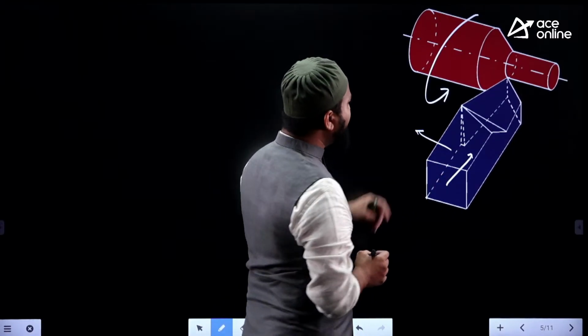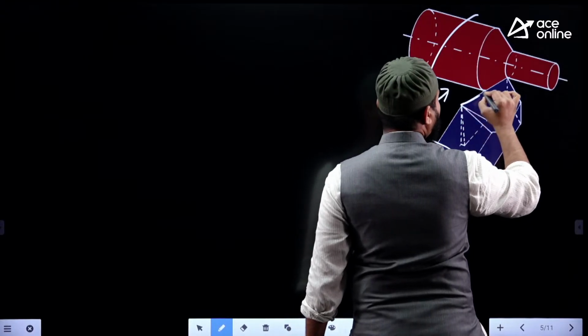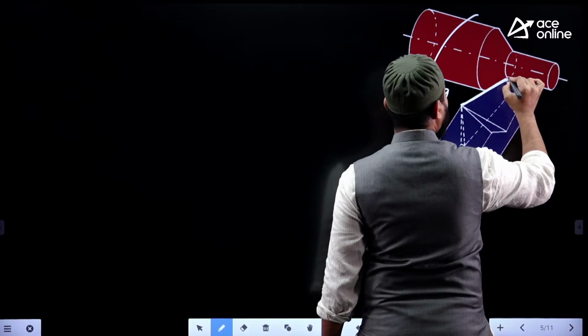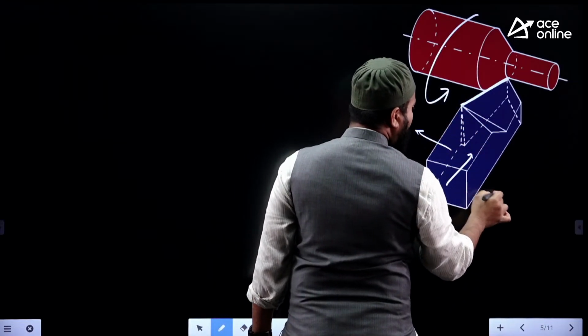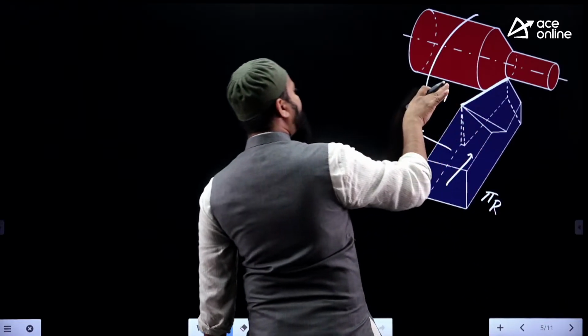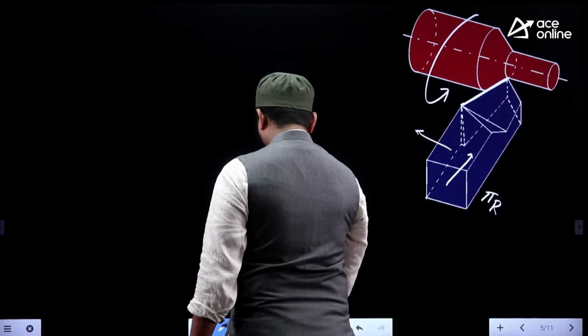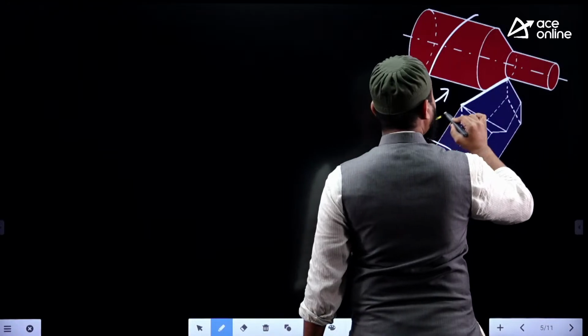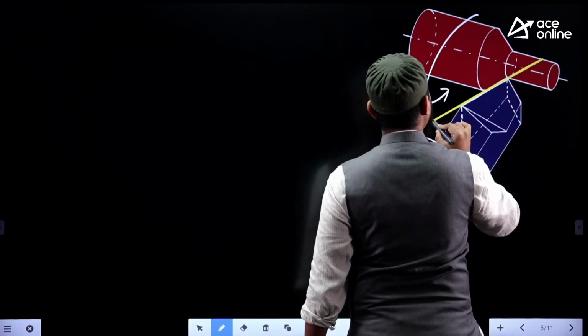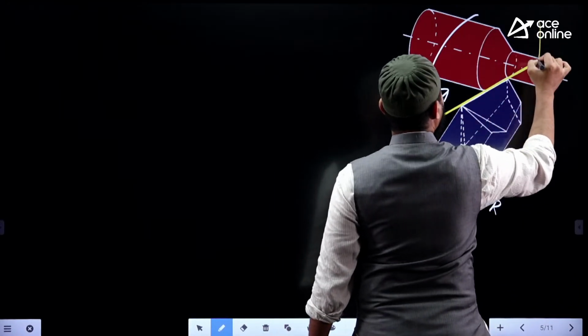Based on that only, we try to draw the tool this way, where the cutting edge is a straight line instead of a curvature, and that line is parallel to the reference plane. It means that the projection of the tool on the cutting plane is nothing but the plane containing the side cutting edge.